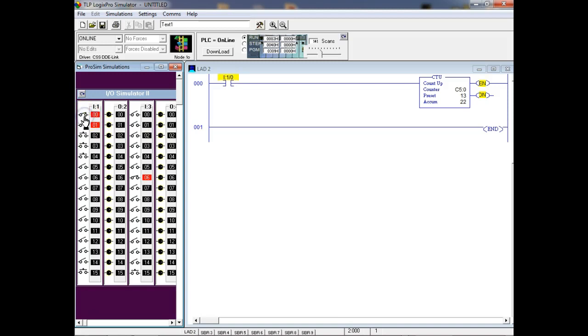So notice I can leave that counted. I can leave it down there forever. How many times did it count? So the only thing it's looking for is that transition. We call it edge trigger. When that input goes from here to here, it doesn't look at anything else.